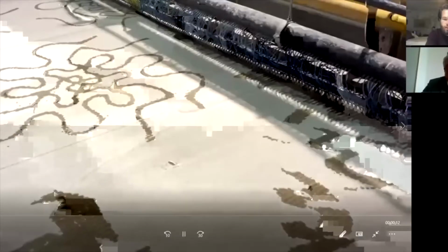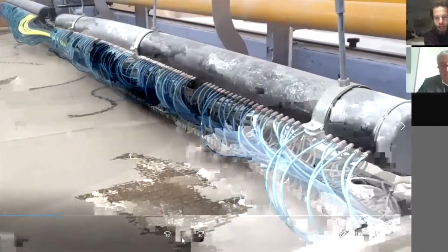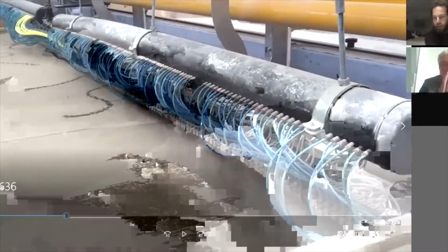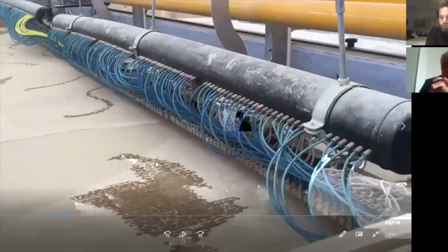How long does the liquid take on the powder to become solid? The minimum curing time is one night, one day, let's say. And of course, you have to handle them with care. Fragile. So the printer puts the powder down after the wet layer. It does dry layer, wet layer, dry layer, wet layer. Yeah, the process is continuous.